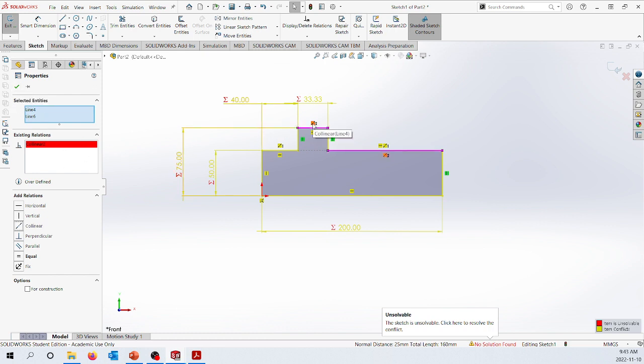And you see, they're showing up in red here, and a bunch of things are showing up in yellow. What that means is there's something like a red relation means I can't resolve this. Something is broken here. These two can't work together. Yellow means I still can't resolve this, but I can't figure out why. The reason I can't resolve these is because these can't be resolved. I need to do something about this bad relationship before it can start doing math. So yeah, basically yellow over-constrained, red impossibly constrained.